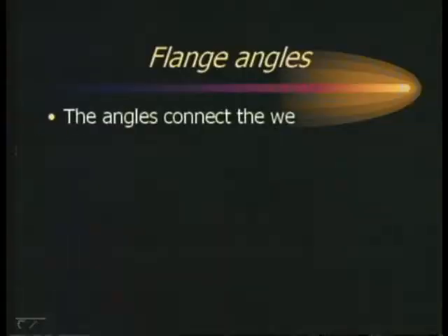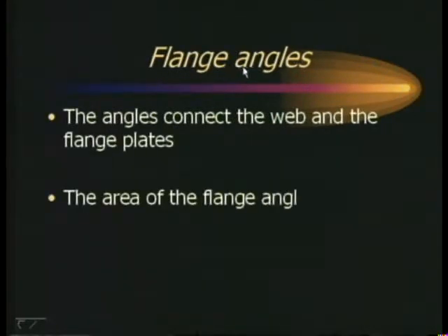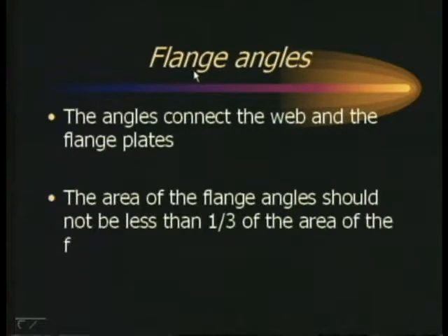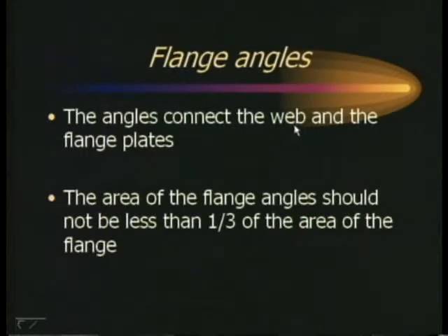Now what next? Flange angles. What is the main purpose of these flange angles? We have seen just now, they take some bending moment, that is fine. In addition to that, what is their duty? They keep the flange plates and web plate in their position. That means they do not allow them to move out of place, they hold them in position. So the angles connect the web and the flange plates.